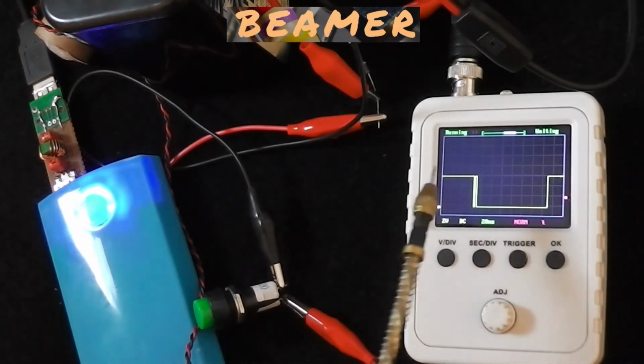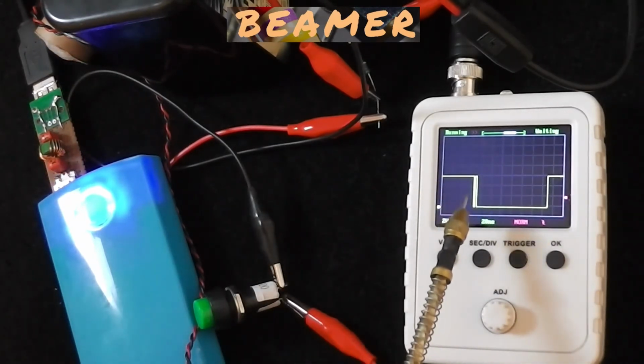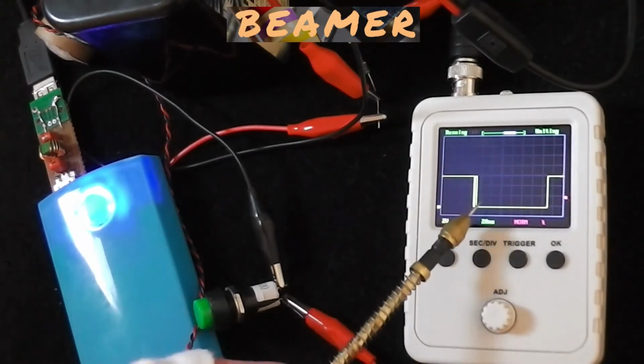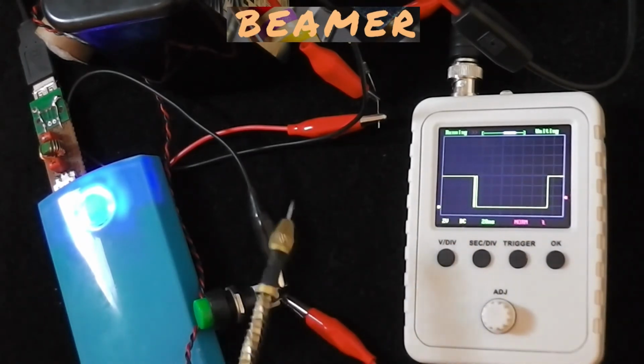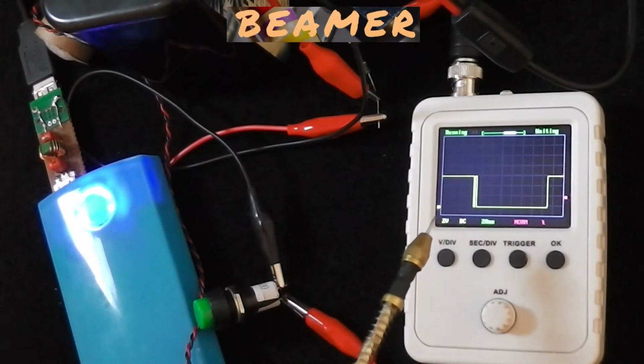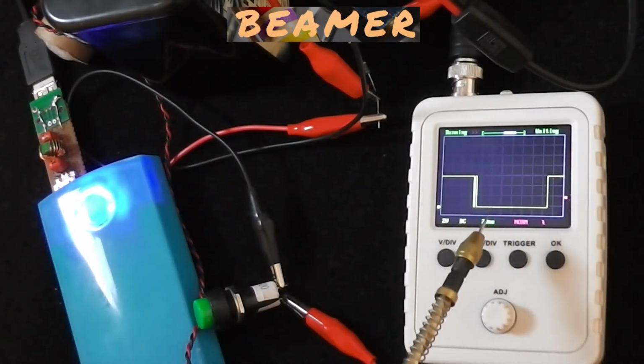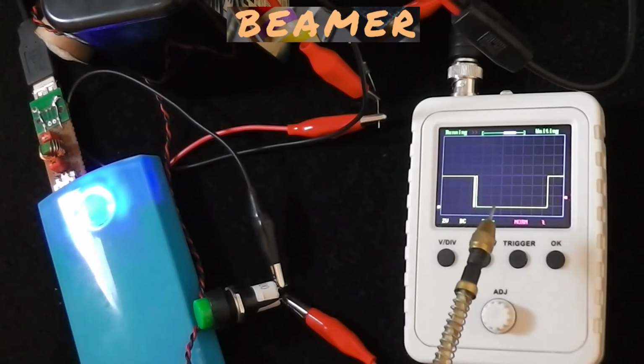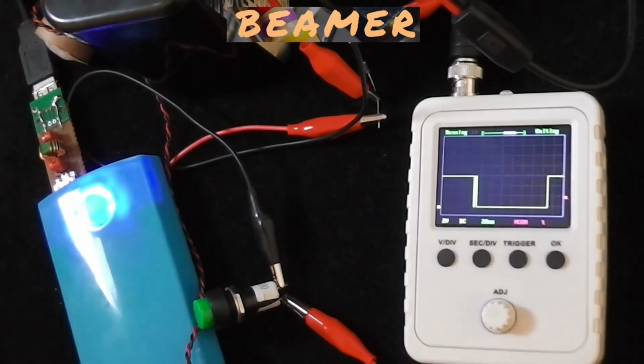Here we are at the leading edge, producing a single bounce there. This is a new switch, so it's going to produce quite a clean image, and as the switch wears, this bouncing will get worse. So it's a kind of switch indecision, isn't it?